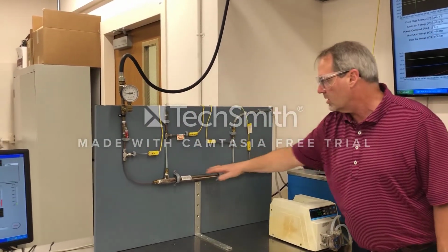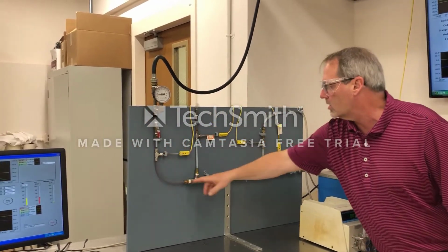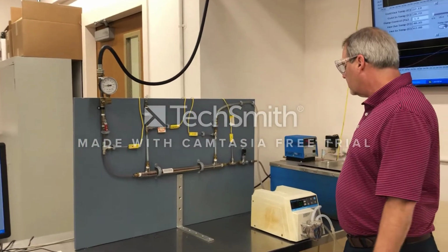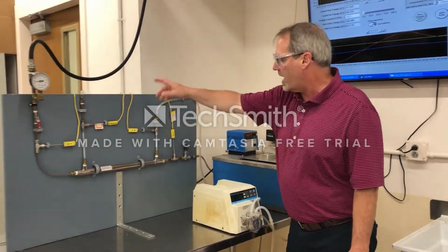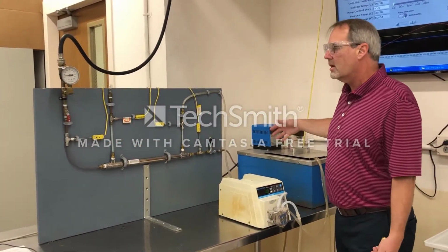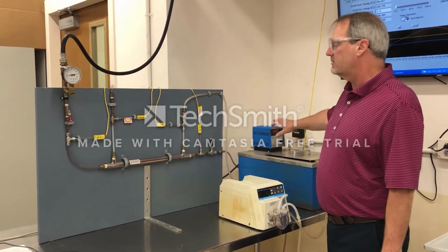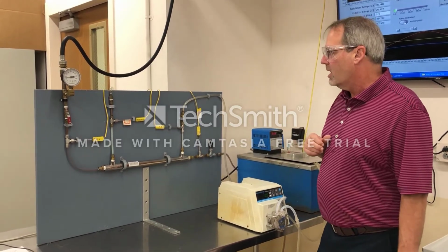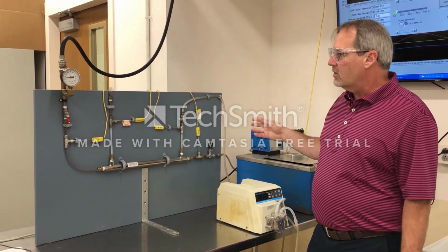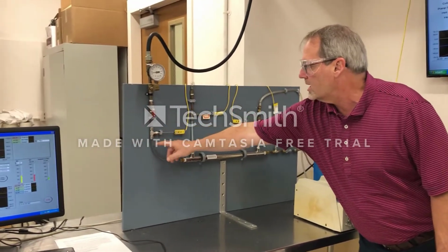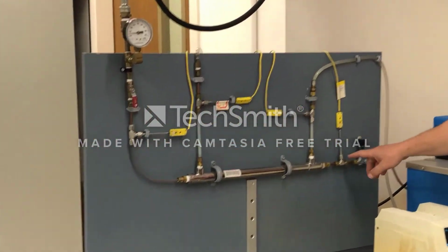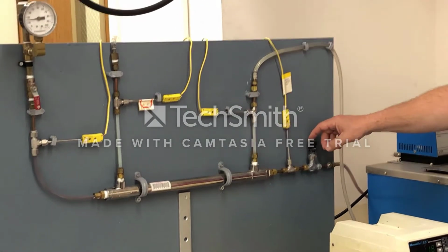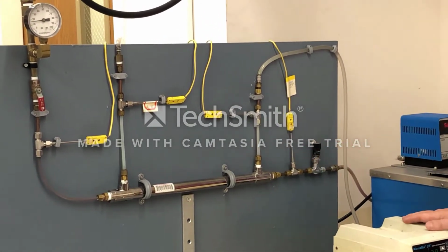So we have hot water on the shell side and cold water on the tube side. The house cold water goes in the tubes and then out, and it's disposed of. The hot water recirculates into this reservoir, and we maintain around a 55 to 60 degrees Celsius hot water bath. The other thing you'll notice is that for our cold water in, we have a thermocouple. Cold water out, we have a thermocouple. And then we have a valve here. So this is a needle valve that we can adjust the flow of cold water.